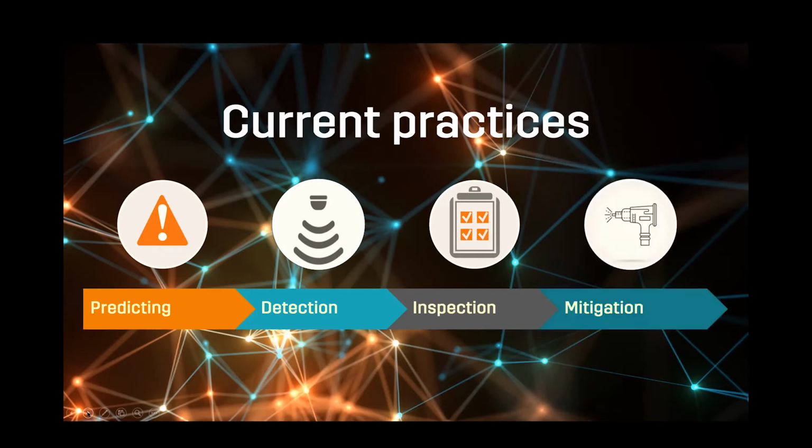And then on to our final current practices, around the mitigation. That's really looking at the different mitigation efforts that we have when we find corrosion under insulation. Typically, these involve blasting and reapplying a coating system. So again, we are seeing new technologies coming through for blasting, whether it's dry ice blasting type techniques, and different preparation methods, and new coating systems as well. So we have various different coating systems that are coming through that can help reinstate the pipework to its